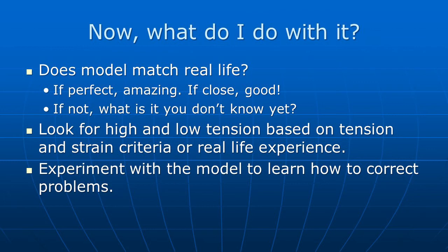And so you can plot things out and see, what are your peak tensions? Where are your big tension drops over rollers? Could those be problem areas for wrinkles or slipping?